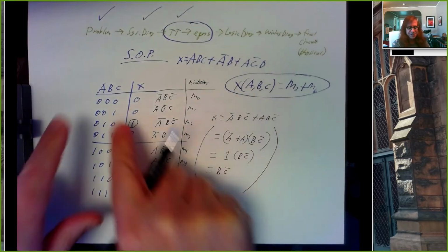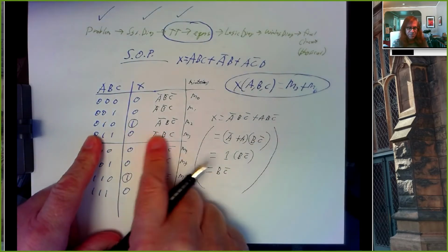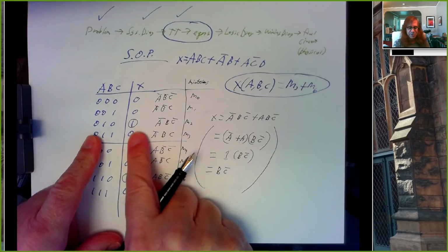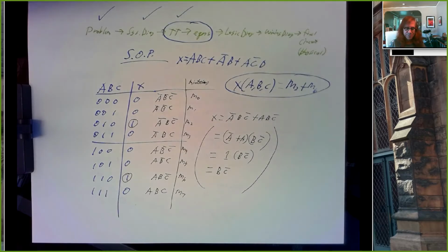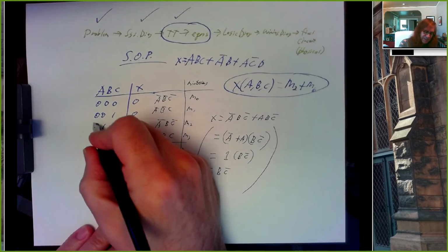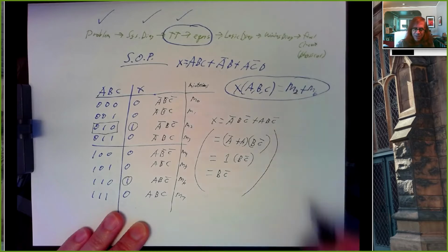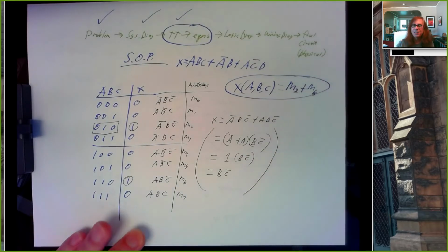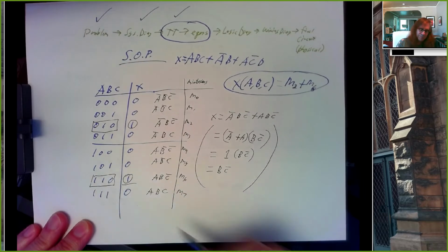The ABC tells us that if we put ABC in this order, then we want a 1 when minterm 2 is active, or when minterm 6 matches the inputs. And if you think about the binary, this 2 down here really tells me the values of A, B, C should look like the binary number 2, 0, 1, 0. And this 6 down here tells me that when the binary number corresponding to ABC looks like 6, 1, 1, 0, we want an output of 1.